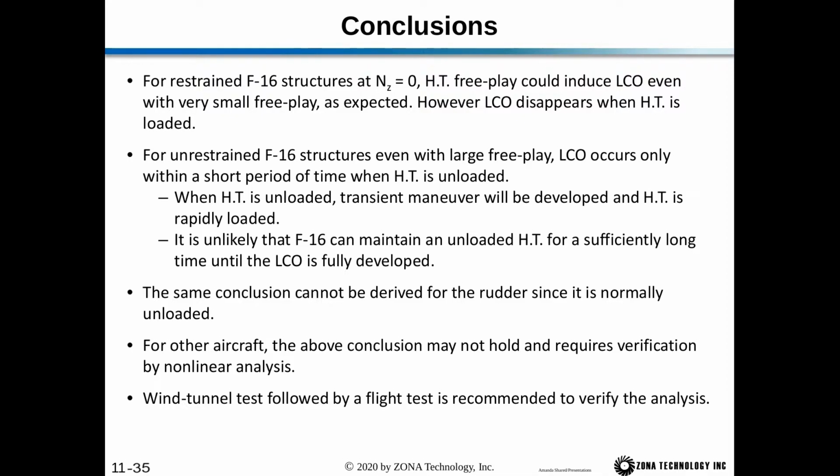When the horizontal tail is unloaded, a transient maneuver will be developed, and then the horizontal tail is rapidly loaded again, because it's very hard to keep the aircraft in a condition where the horizontal tail is unloaded. And it's unlikely that an F-16 can maintain an unloaded horizontal tail for a sufficiently long time until the LCO is fully developed. Now, however, this same conclusion cannot be made for the rudder since it is normally unloaded. Now, for other aircraft, the above conclusion may not hold, and it requires verification by the nonlinear analysis. And additionally, wind tunnel tests followed by a flight test is recommended to verify the analysis.